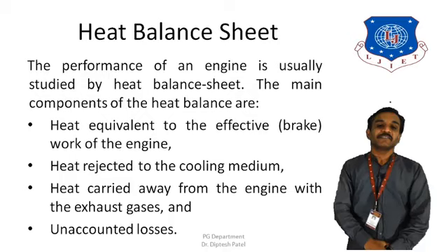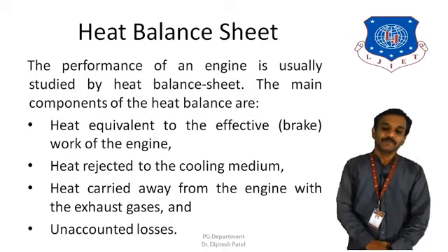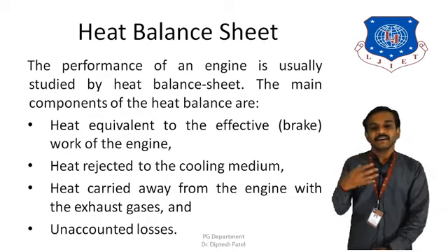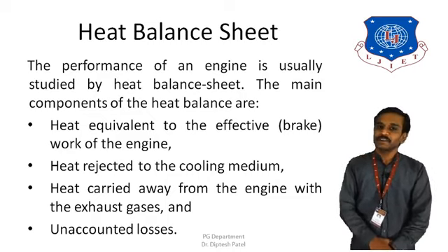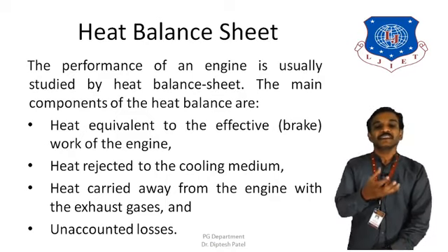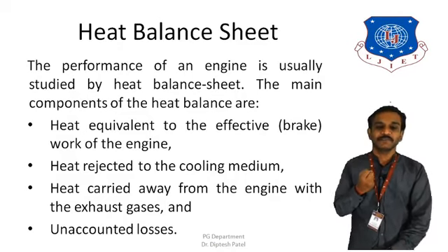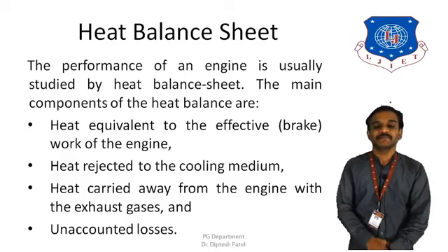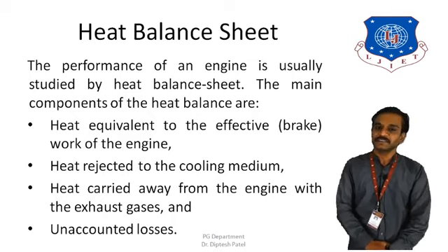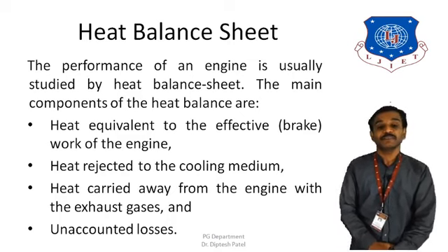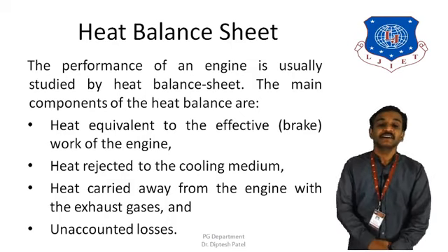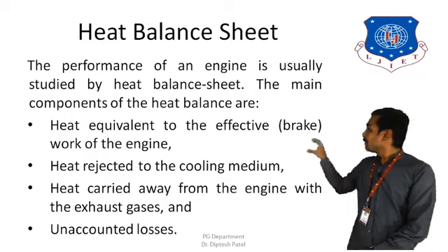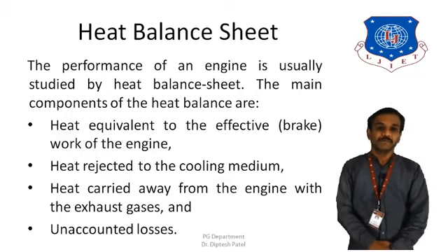The second component is heat rejected to the cooling medium. Since we provide the cooling system in the engine, it also carries away a certain amount of heat, because we don't want to damage the different components, and sometimes the heat in the engine goes very high. So a proper cooling system is required, but it also consumes a certain amount of heat that might be utilized to generate power. So the second component is heat rejected to the cooling medium.